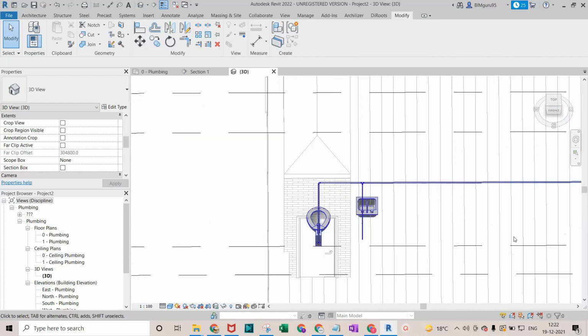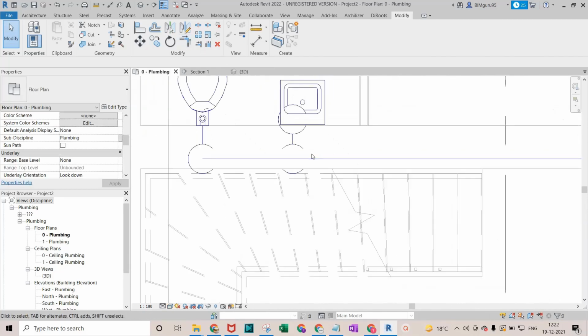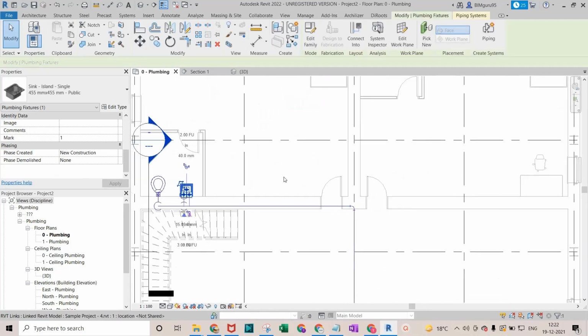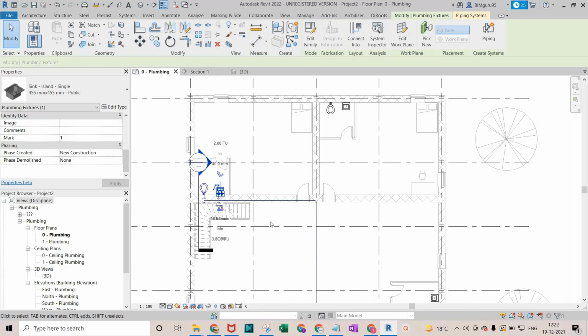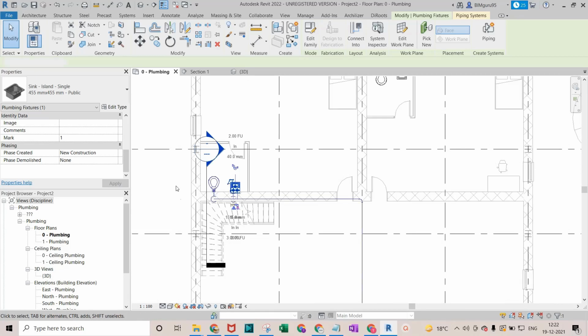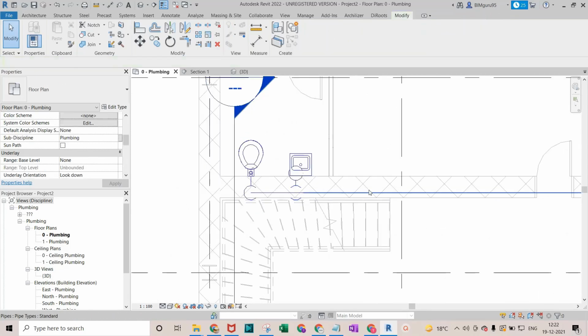Should cancel this one. Okay. I'll go to my plan again. First of all, we'll go with the water supply connection, the cold water connection only. One thing I forgot to mention: sometimes we consider different pipes for the flush for the toilet WC, which carries non-potable water, but potable water for the wash basin.